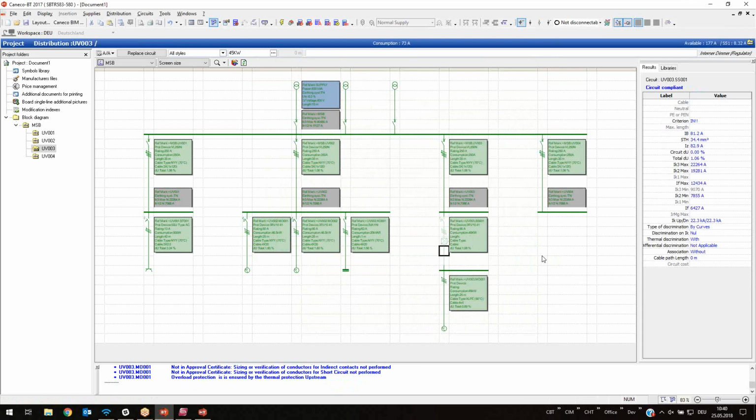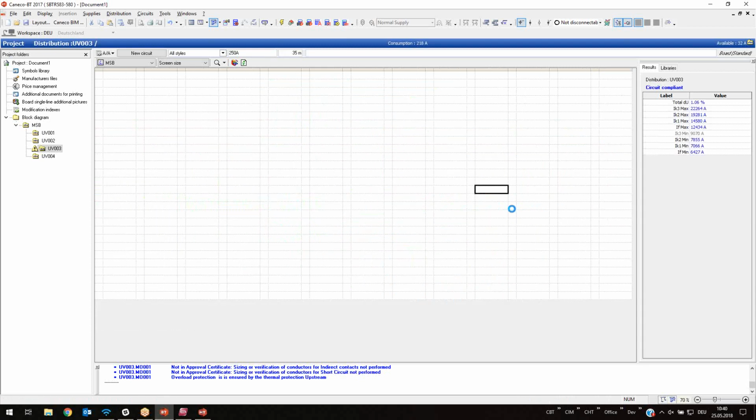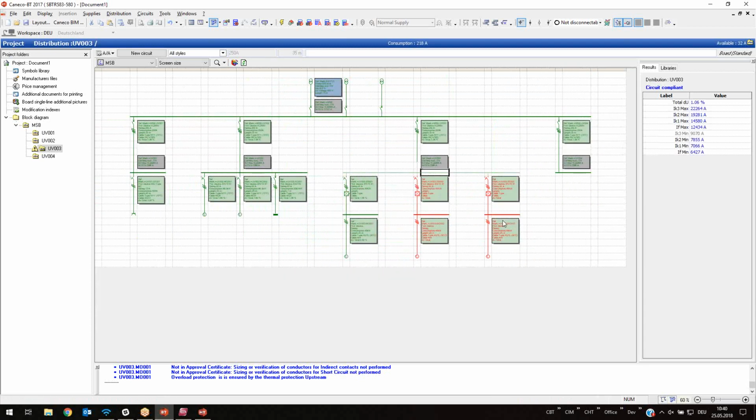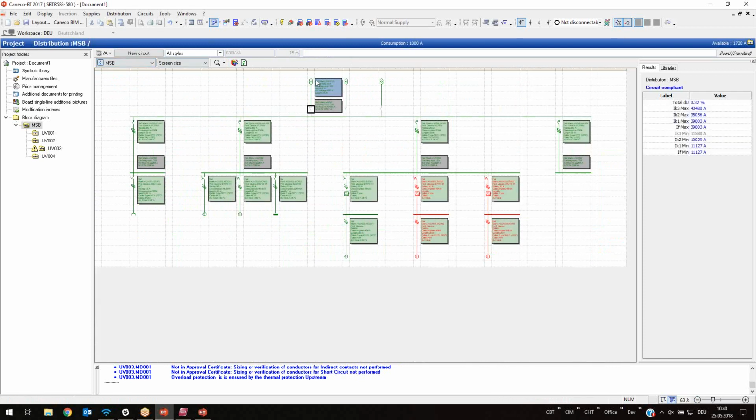Let's suppose you have more drives, and during the operation of this project, some of the drives have a contribution in terms of power which is negative. So they are not consuming, but they are bringing energy. They are feeding the cabinet, and delivering a short circuit current. Like a generator. Yes, correct.